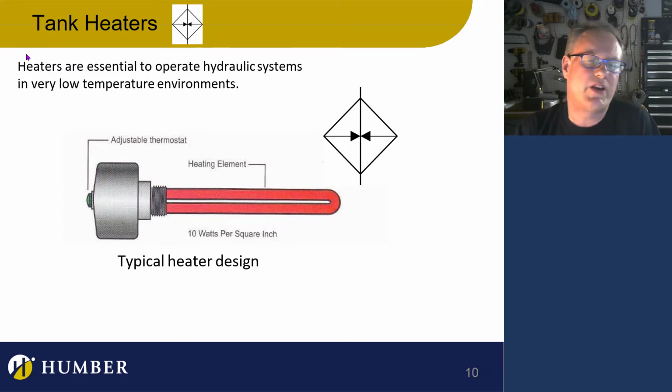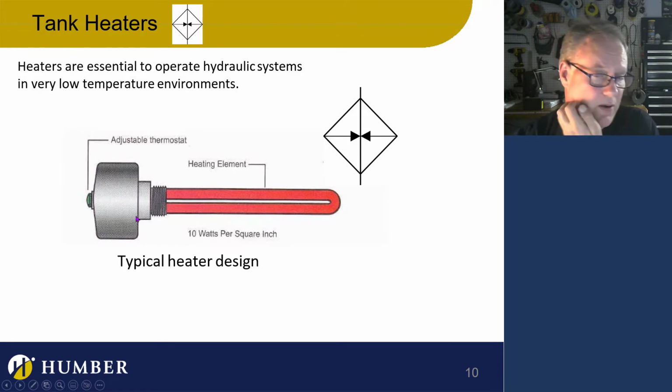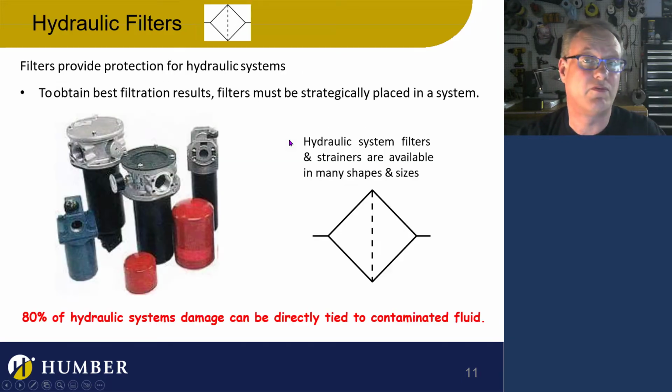Just like when you heat up your car on a really cold day, you want to get your engine running and your transmission running and your bearings going and everything else. You start your car, you let it idle for 30, 40 seconds or whatever, and you put it in gear and just drive it really slowly for the first few minutes to get everything warmed up. That's exactly how you're going to deal with a hydraulic system that's cold. But if you need to have a heater or service a heater, it's just going to be threading right into the tank, and that's the symbol for that heater. So essentially, there you go.